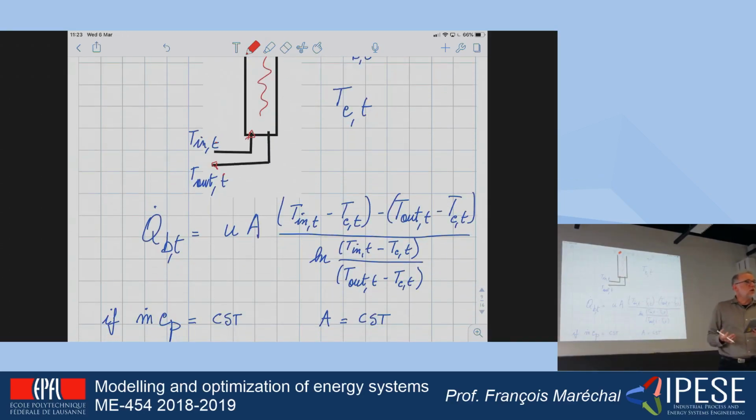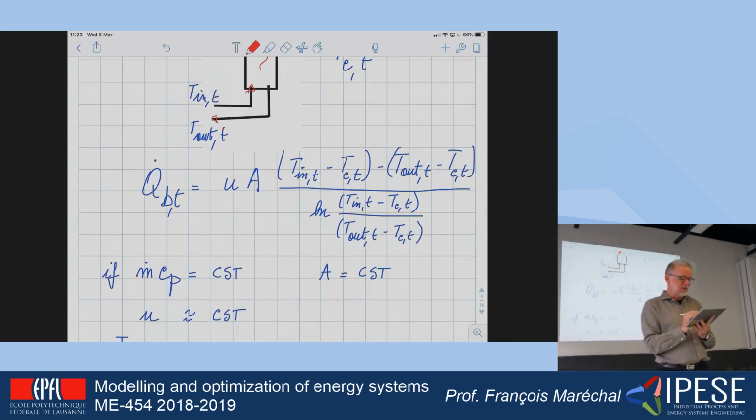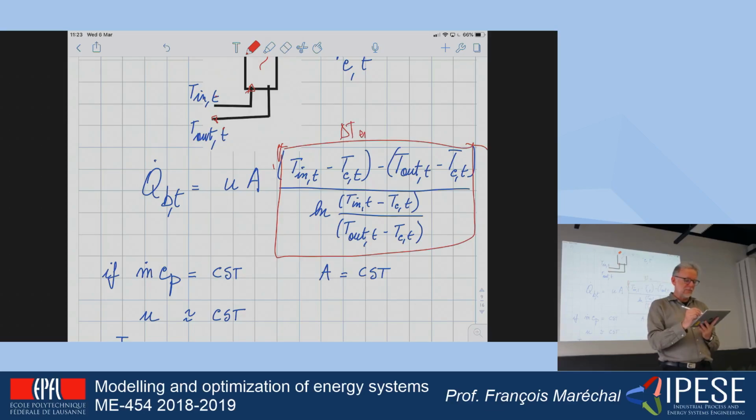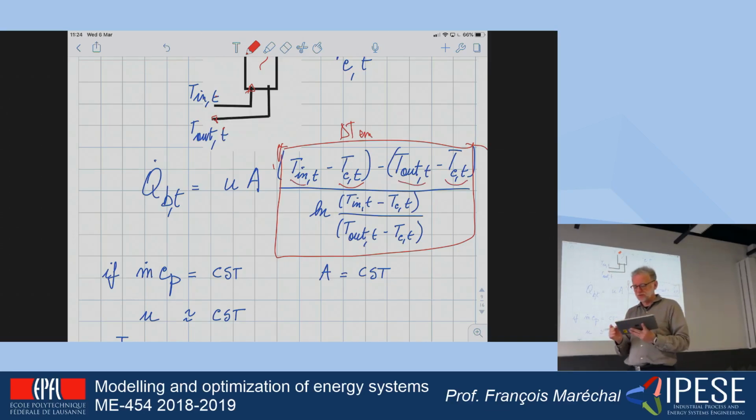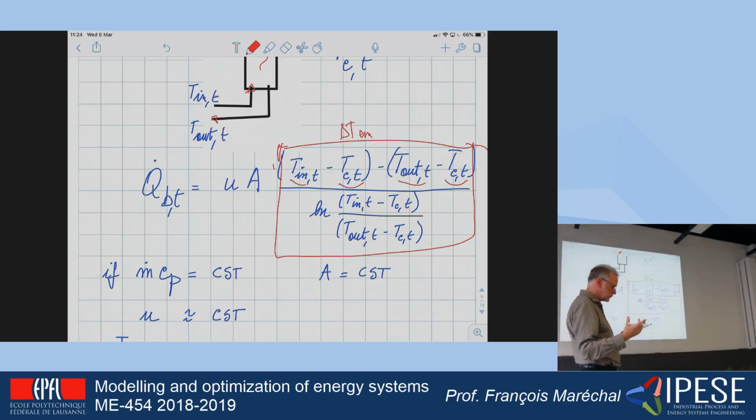This heat load is also following the heat exchange formula. Okay, so it means the principle of the heat transfer, which is expressed by the logarithmic mean temperature of the heat exchange, which is shown here. Okay, so this is the delta T Lm, in which you can see that there is a constant value here, which is the comfort temperature, which is not changing, while you have the inlet and the outlet conditions of the water. And here I'm making the assumption that it follows the countercurrent principle.